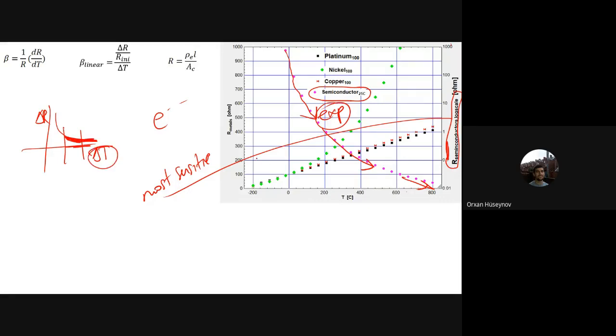That is the bad side of exponential functions for temperature measurement. Therefore, semiconductors are not used for this whole range, but in some range around here, where you see the linearity again. But if you always use the linear part of the semiconductor, you can have some errors because it is not perfectly linear. It is approximately linear, so you can have an accuracy problem here.